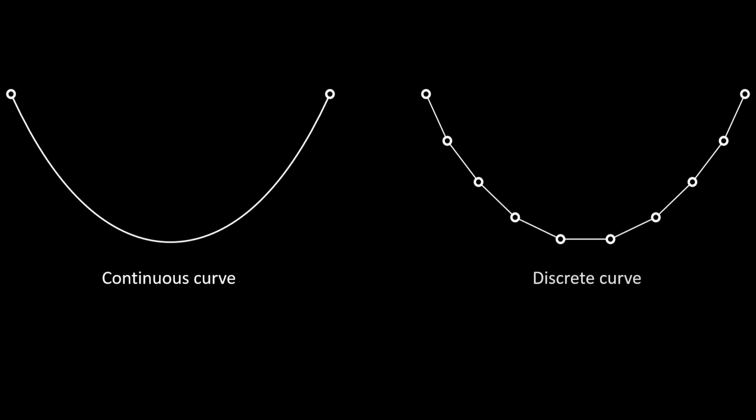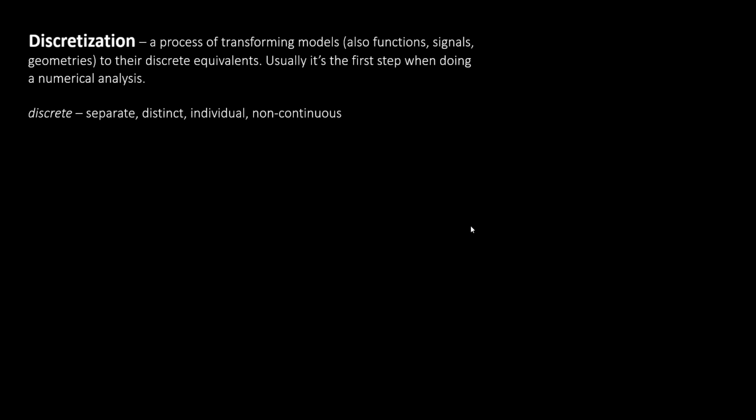There is a difference between continuous and discrete objects. Basically, the native kind of geometry for Rhino is NURBS geometry, as you know. So before we process anything native to Rhino, we need to convert it to a discrete object. We would convert a NURBS curve to a polyline. That's something that I probably told you about some time ago, and you should remember this term.